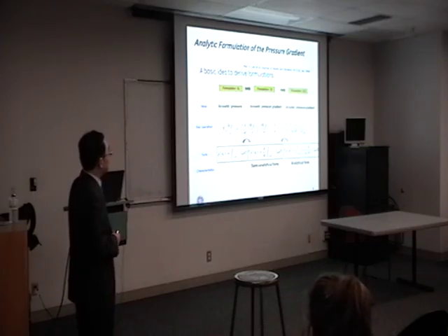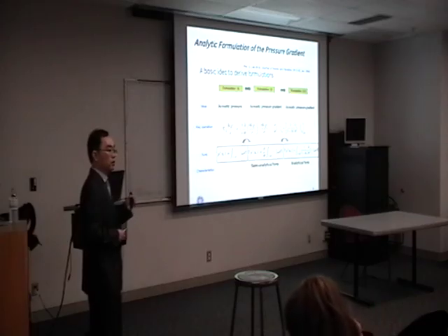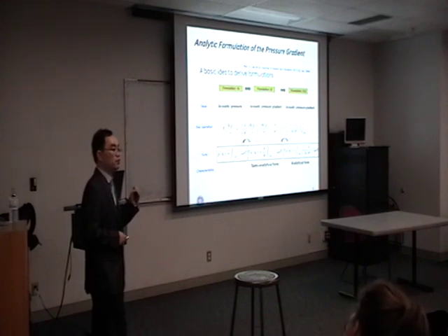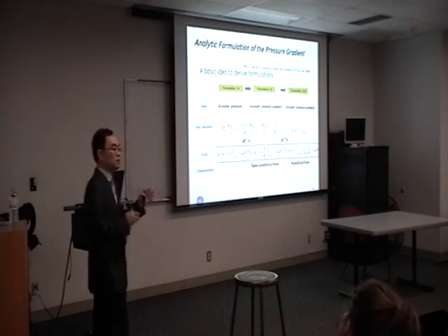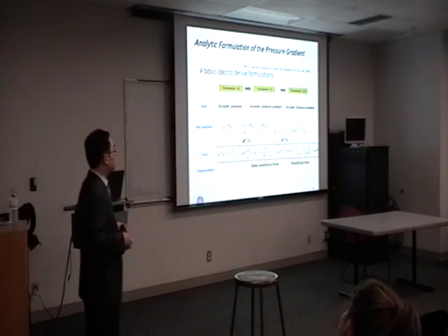I did one more step. I converted the observer time derivative into the source time derivative. The observer time means the time when the observer receives the sound. The source time means the time when the acoustic is actually generated. So there is some time delay between observer time and source time, which is a function of the speed of sound and the distance.